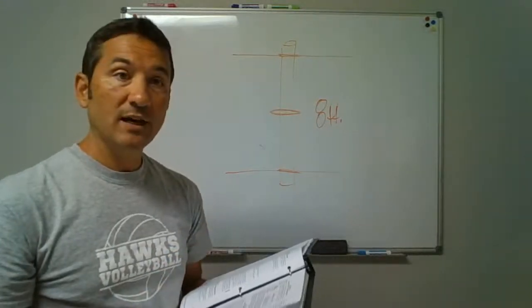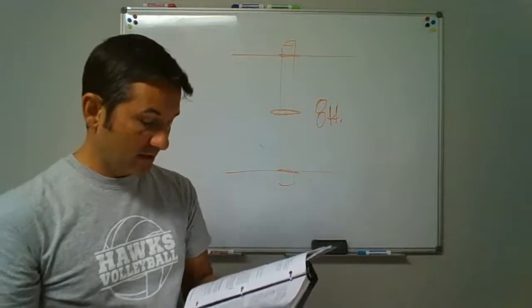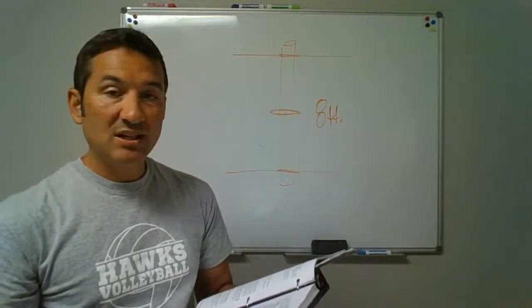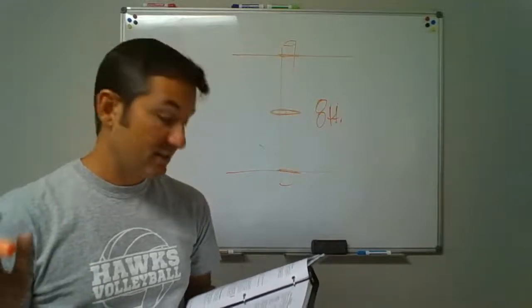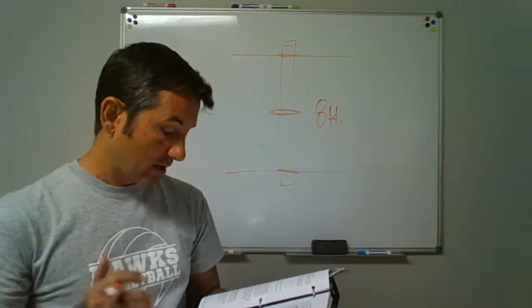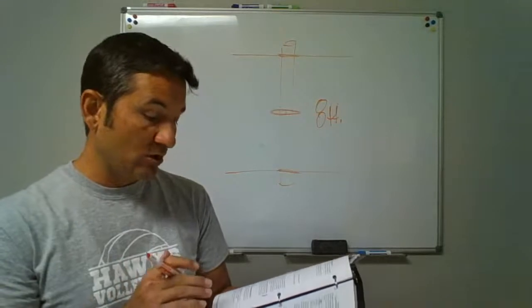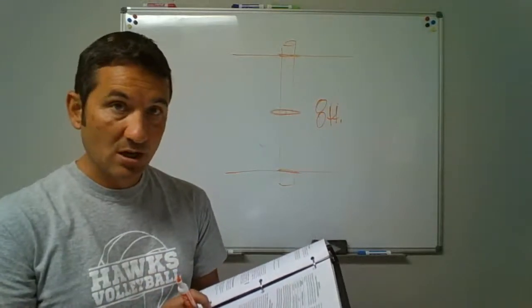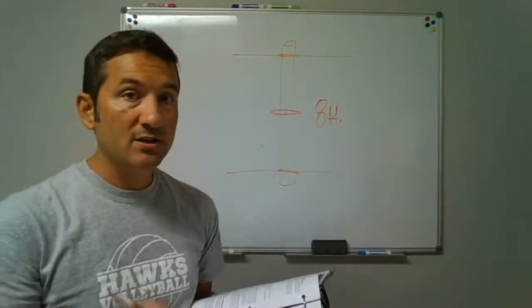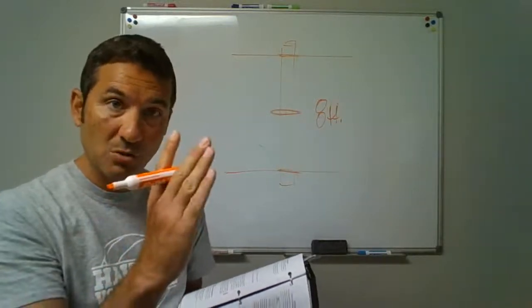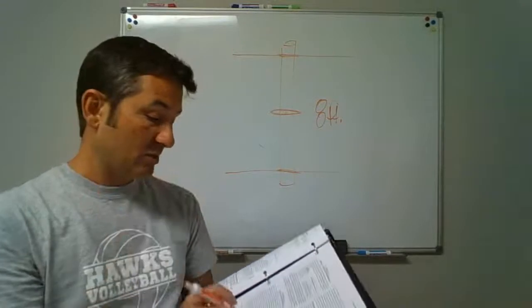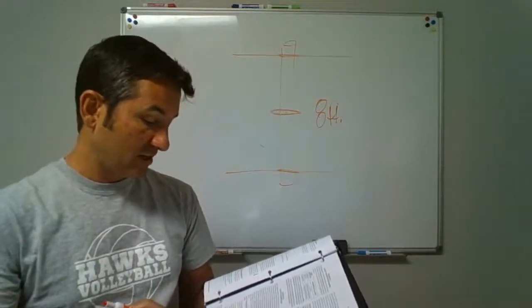Okay, the last stuff I've got, 8 minutes to cover it real quick. Testing and inspection. Once we get all the pipes run, we got to cap everything off. We got to test it. It says we got to test them according to these. It even gets into the type of test gauges that you use. If it only requires a 5 PSI test, you can't use a 100-pound test gauge because the increments are too small to really get a good read. So it talks to you about the test gauges.